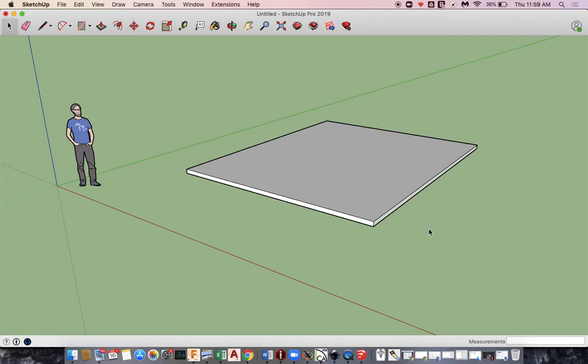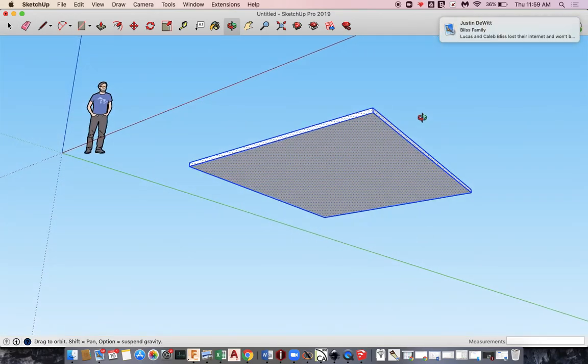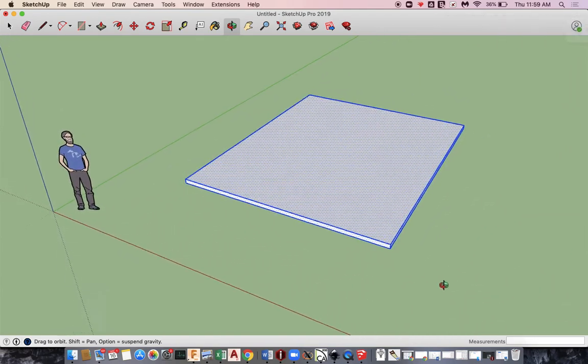So, to collect this together, we're going to create a group just like Tinkercad. You need your select tool, so spacebar, and you're going to triple click. Depending on your mouse sensitivity, you might have to click faster or slower, but it should select everything that we drew for the floor here. So 1, 2, 3. Notice that selects both the face, the edge, and all the stuff underneath. If I orbit up, notice it'll be on the bottom side also.